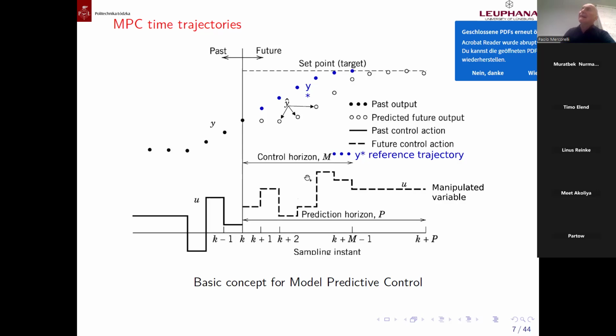I will calculate my manipulated values until the end of the horizon, and then each time I will calculate again, because I don't trust what I am predicting today for when already is tomorrow. I mean, each day it is reasonable to think that we can repredict. This is the sense of the model predictive control.